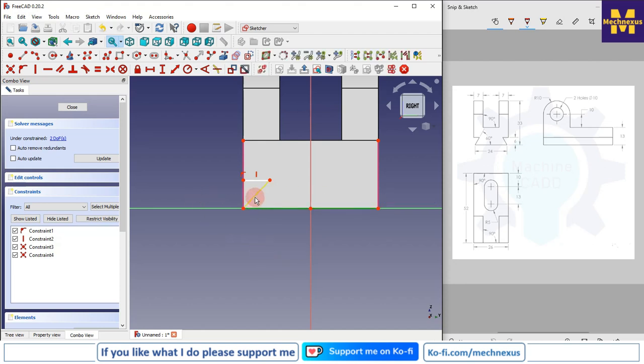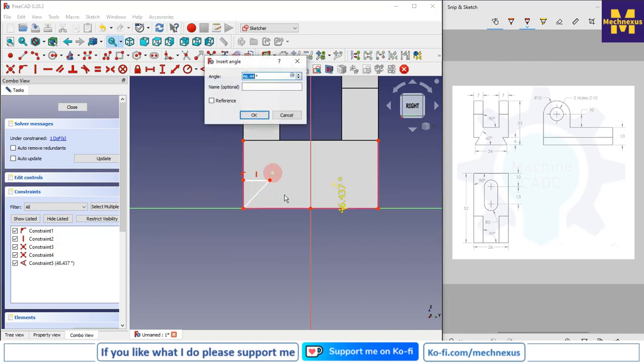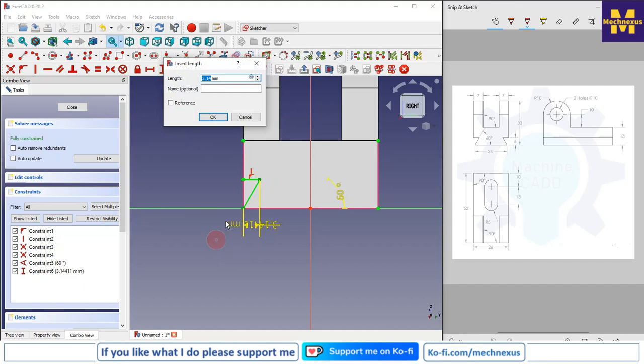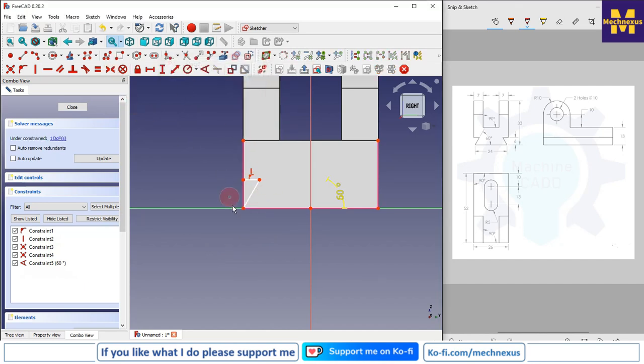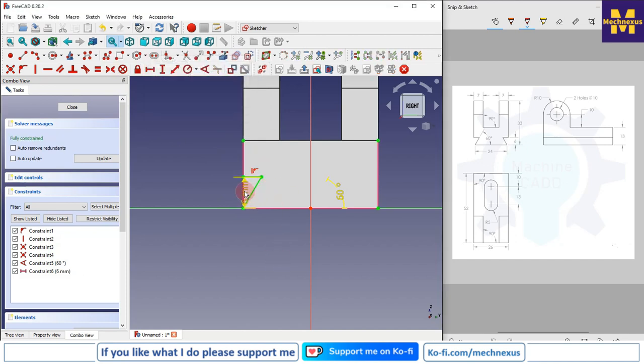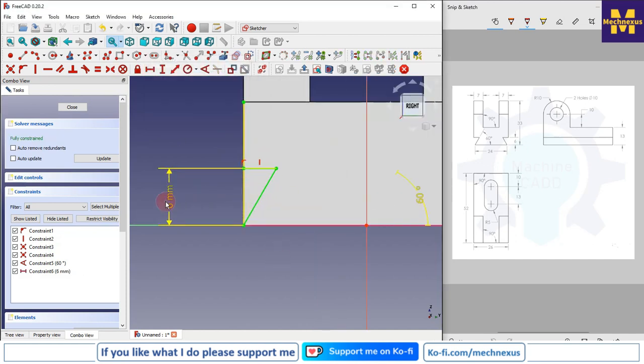So I will select this line and this line, and I will give the angular constraint of 60. Height is 6 mm, so I will give the vertical this point and this point 6 mm, and I will close my profile.